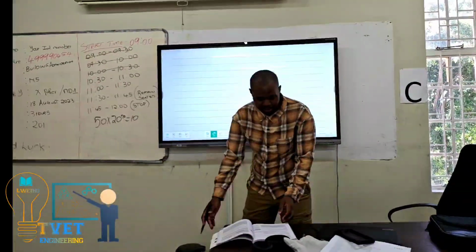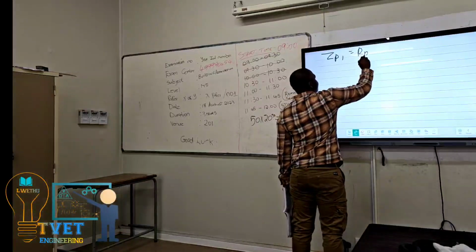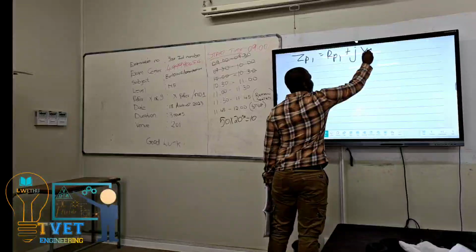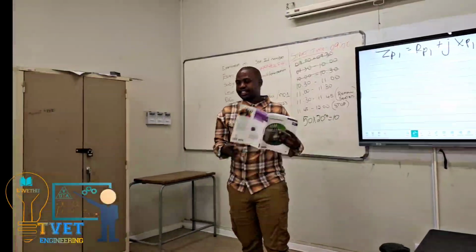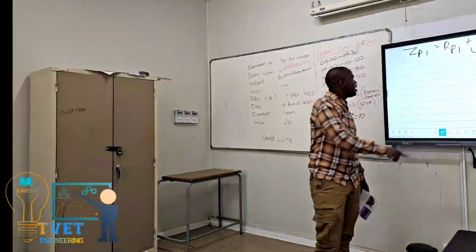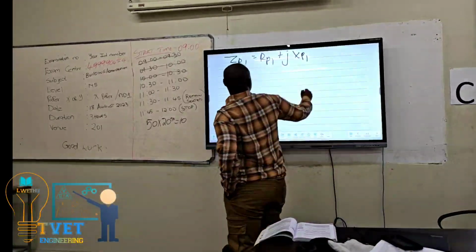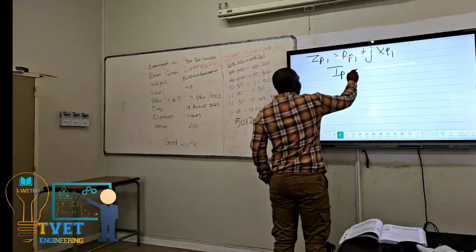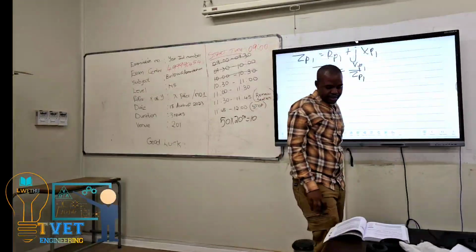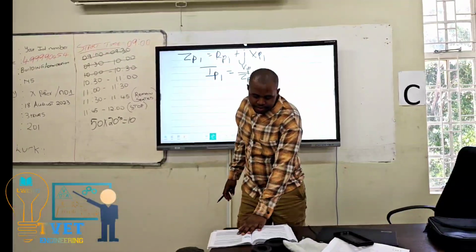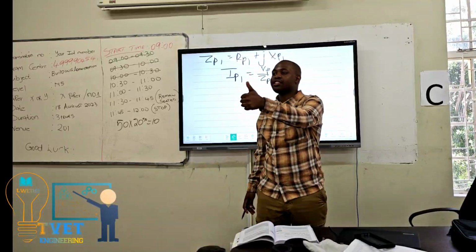If the motor is connected in delta, the phase voltage is equal to the line voltage. If it is connected in star, the phase voltage is equal to the line voltage over the square root of 3. And also you know the impedance per phase, R plus jX. Remember, motors are inductive. And from Ohm's law, the phase current is equal to the phase voltage over the impedance.